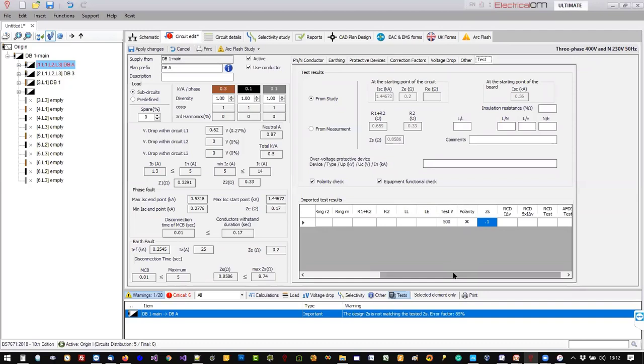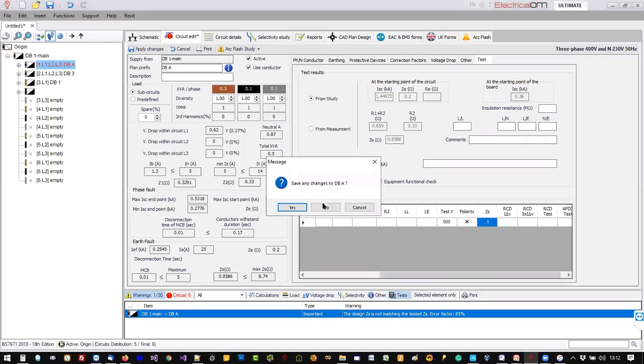I think also one of the things that we're looking to be doing, we're going to make that user selectable, aren't we, as well? So you can set your own percentage parameters. Some people like to go with the parameters as per the British standards for the instruments. So instruments themselves for certain tests allow a certain percentage. And also, we're using ZS here, but ZS isn't the only calculation check that we're doing on this basis either. There are other parameters there that are being done as calculation checks as well.